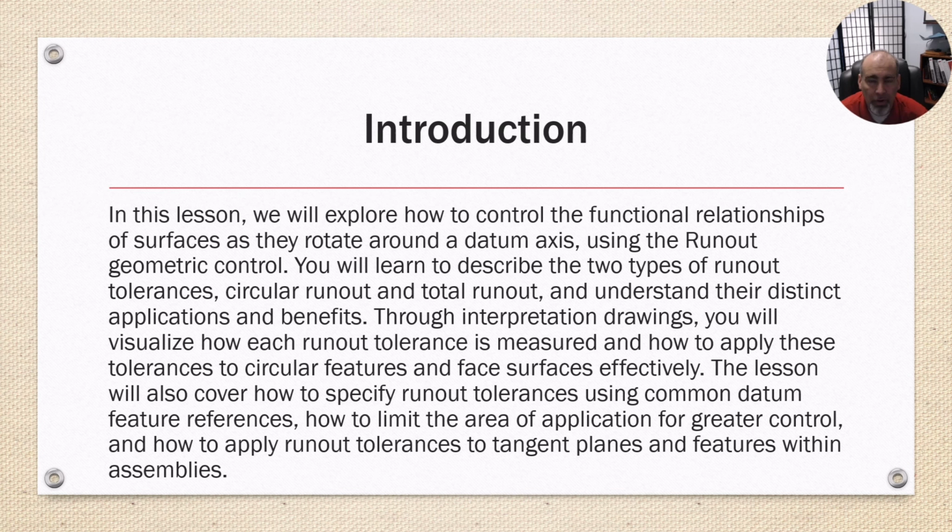The lesson will also cover how to specify tolerance using common datum feature references, how to limit the area of application for greater control, and how to apply runout tolerances to tangent planes and features within assemblies.